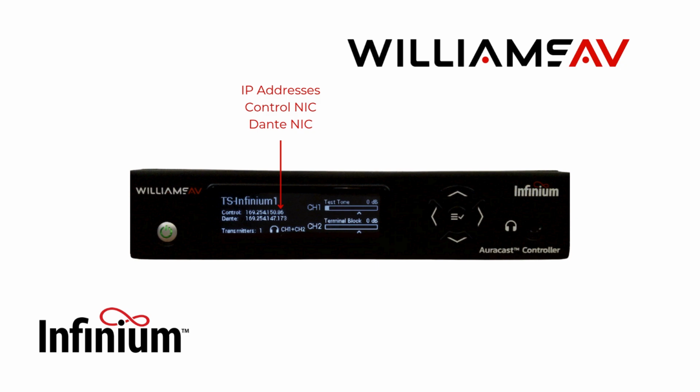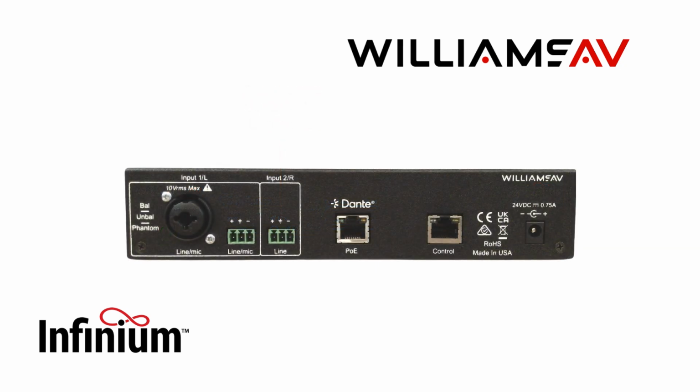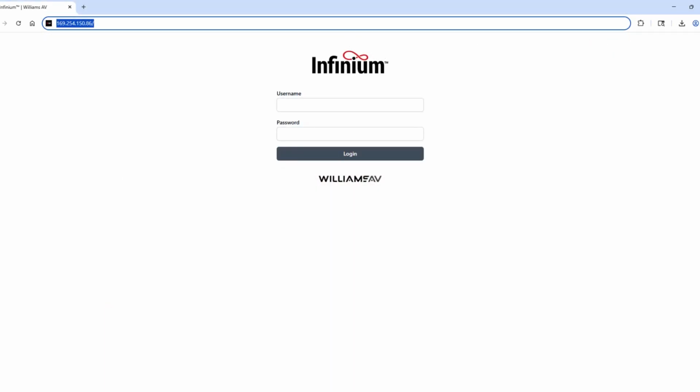To access the web UI, connect your computer to the same network as the Infinium controller, or plug directly into the control port on the back. Then open your browser. Google Chrome is recommended. Then type in the IP address shown on the front panel.